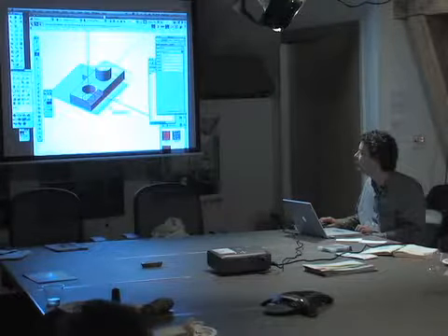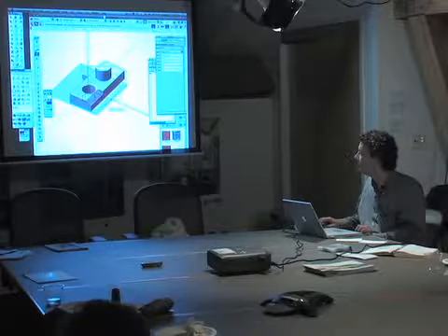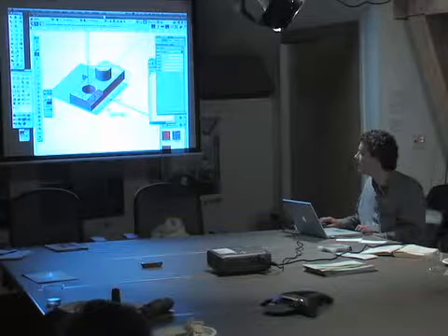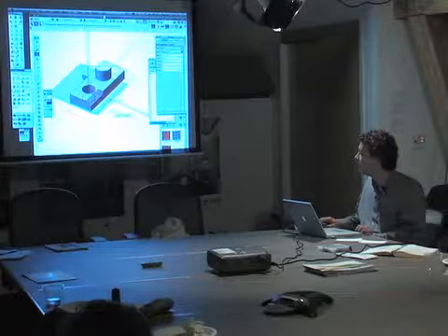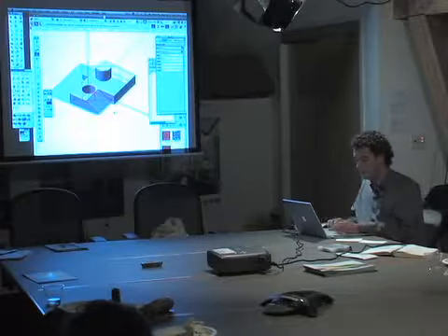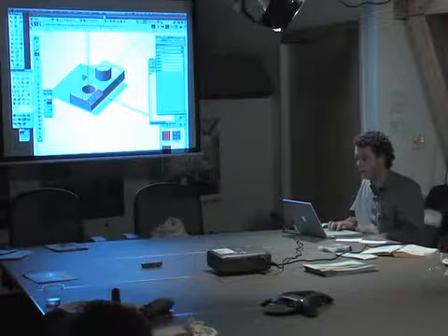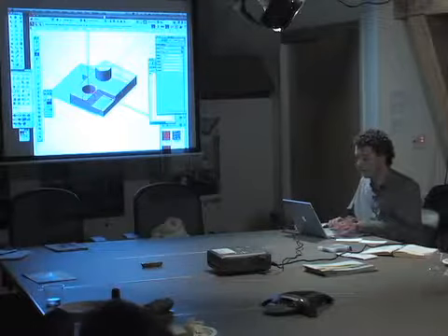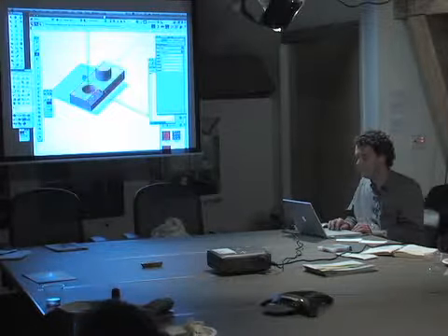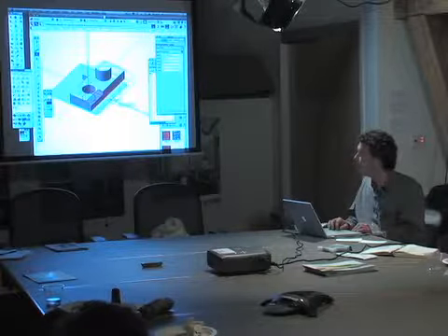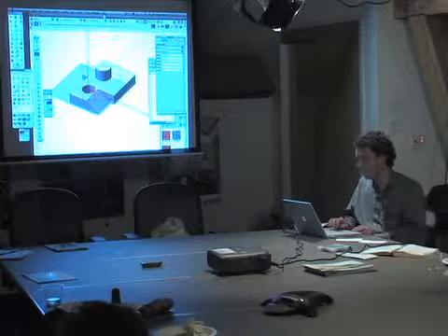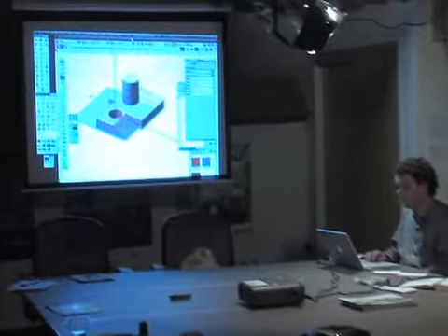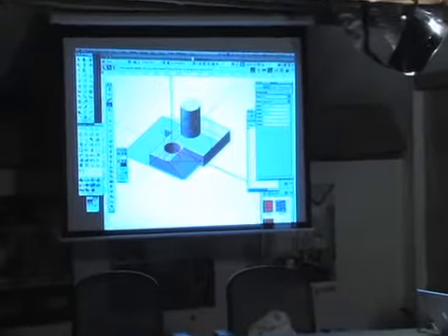So the move face mode will keep this geometry. You can see how this chamfer will stay with it as long as it can. As I adjust this face, this chamfer adjusts automatically. If I undo that and go back to this first mode and select this face, it just pulls the face straight out. So this move face mode keeps the geometry orientation. The push-pull is a great new feature.